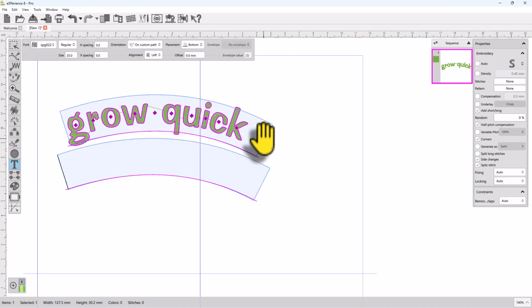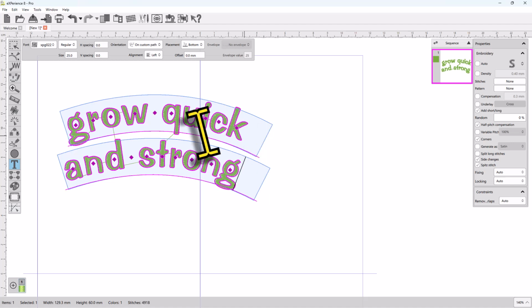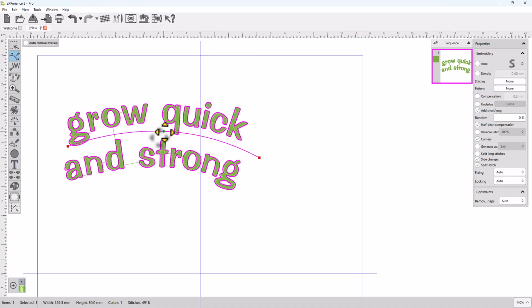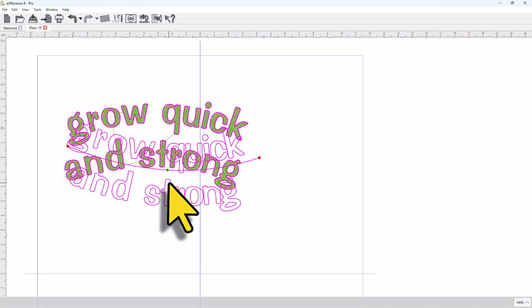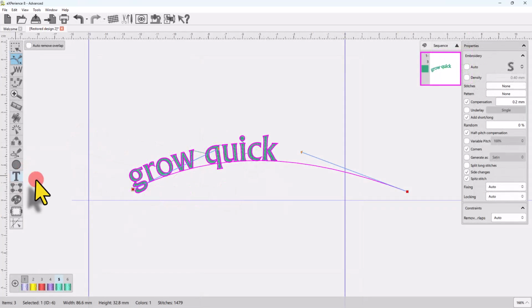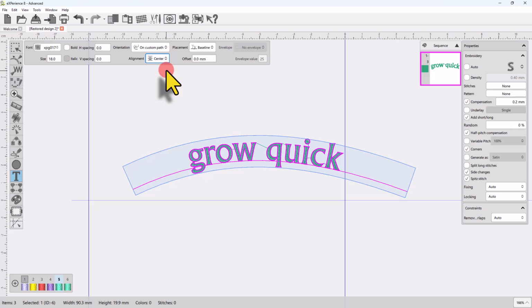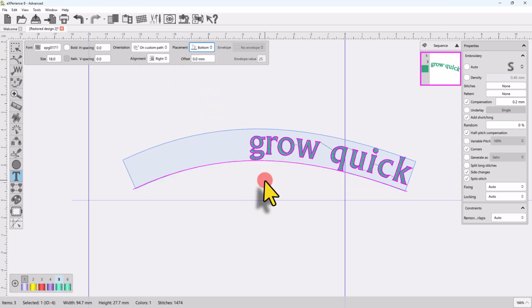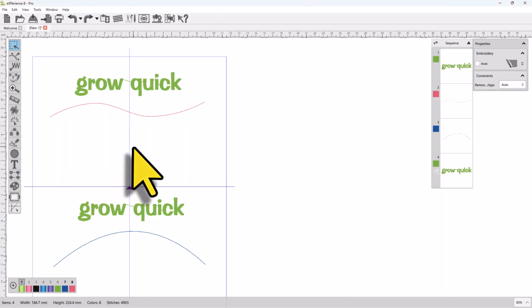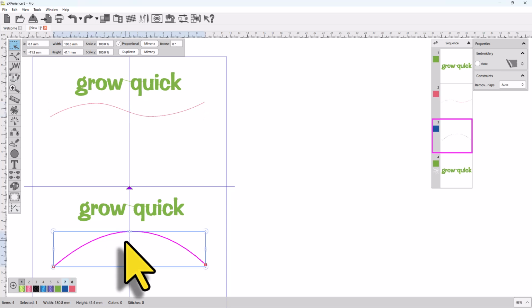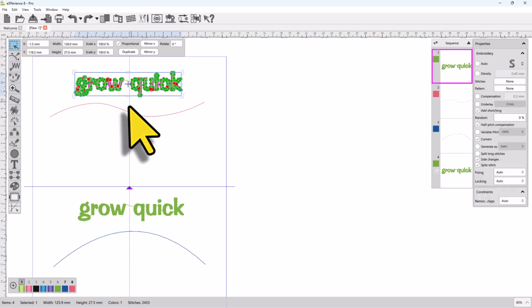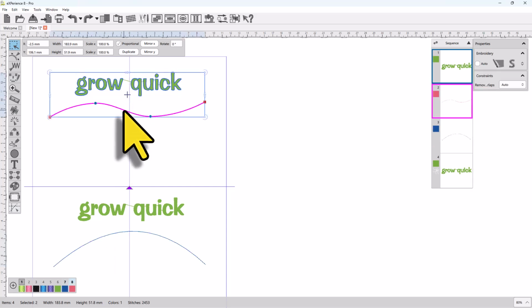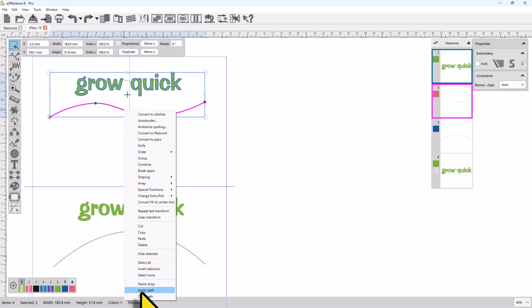You can create multi-line text objects on a custom path as well, and by editing this custom path, you can create unique lettering paths. You can also align the text on the path or adjust its placement on the line. Notice also that you can use any part of your design as a custom path. This is really easy. Just select the text part along with the running line, right-click, and use the Apply Path option.